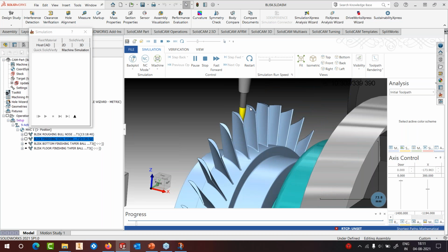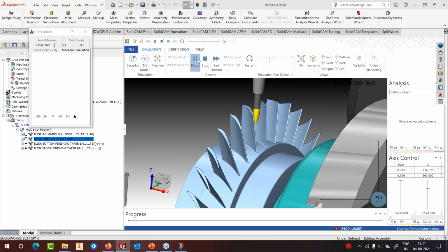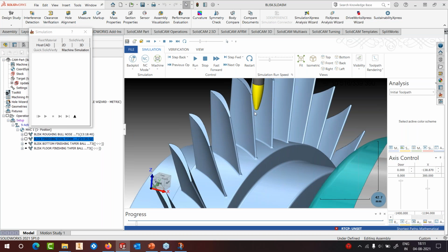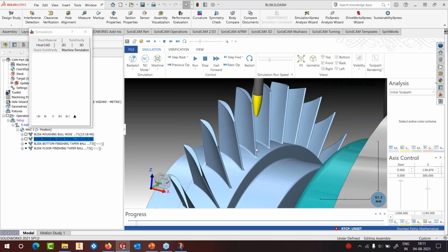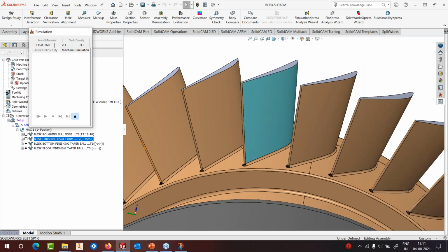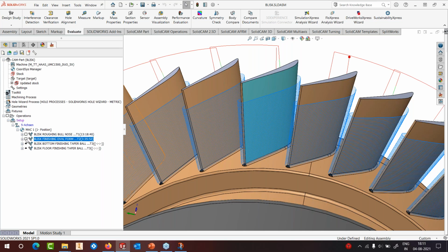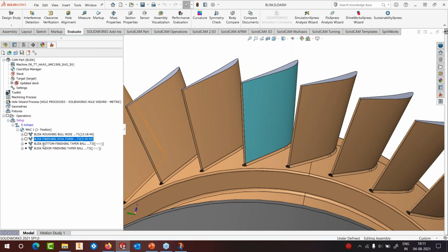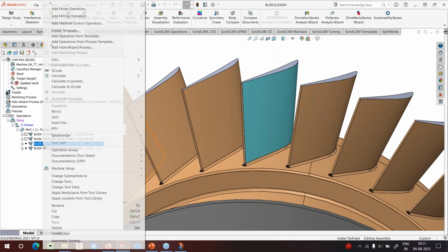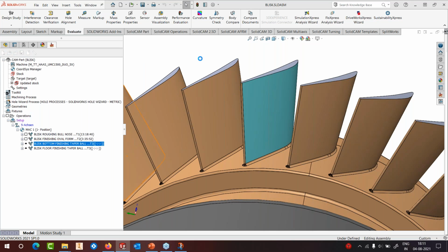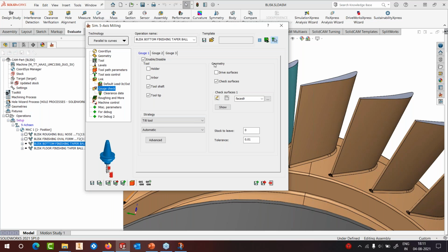But the disadvantage when you're going in such parts is that the tool cannot reach all the way down. So there will be some portion of the material that still will be left out, which will be unmachined. Okay. So for that, what we have done here is I have done the finishing of that short portion here, whatever area that remains. I'm doing it with a taper ball nose. Okay. So here I don't have a choice. I have to use a taper ball nose to finish all the way down.